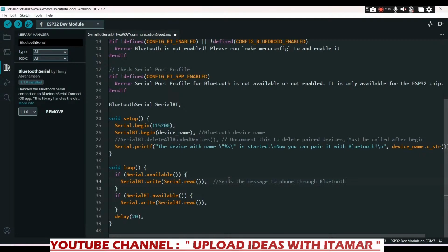So I'm going to be typing a message from serial monitor. When I do enter, the ESP board will send this message to my phone. And the serial write, the one, it receives the message from my phone through Bluetooth. And this message will be displayed on the serial monitor.